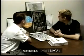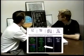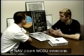How do you know you have LNAV engaged? It says nav mode, NAV. And what is it referencing in nav mode? NAV's referencing the flight plan in the MCDU.